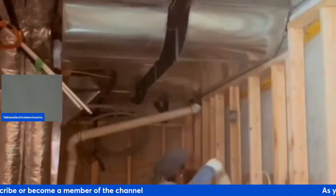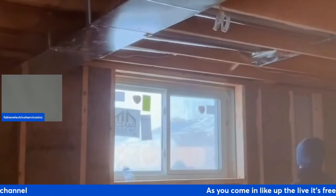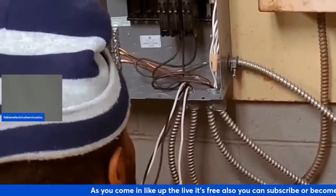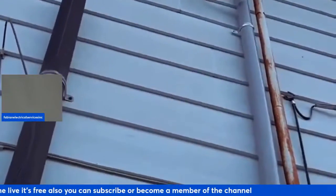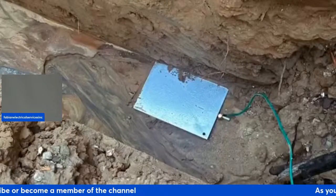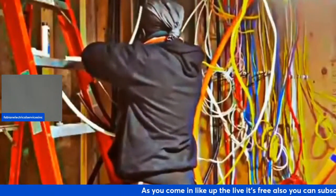Again, what they don't protect against: GFCI outlets do not protect against all electrical hazards, such as a person holding two hot wires at the same time. They are not designed to protect equipment from short circuits, which is the job of a standard circuit breaker. So again, that's basically the explanation of a GFCI.